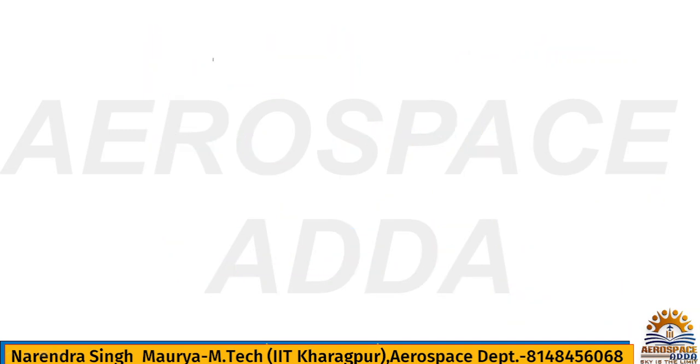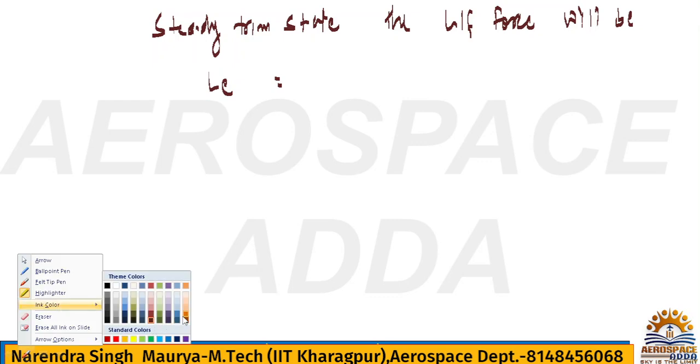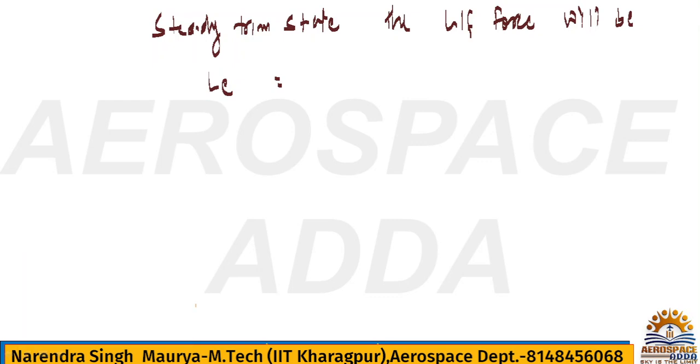Now if you check for the steady trim condition, trim state, what will be the lift force here? L E is the lift at equilibrium. Trim means equilibrium condition. So what is the lift force? Obviously it is half rho V square, but at steady state what is the velocity? It is V naught, so half rho V naught square.